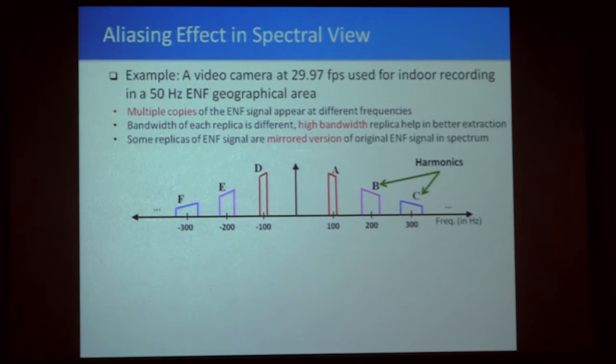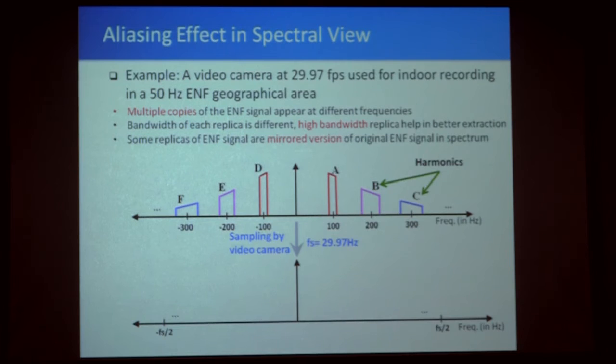So it's periodically tiling with multiples of this sampling rate. So over one period, in this sampled version, we have a periodic spectrum. We just zoom into one period, and we will find that this plus and minus 100 hertz got aliased to just above 10 hertz. So that's why we see the spectrogram before was at 10 hertz. The harmonics were getting aliased to just below 10 hertz, and then the 300 hertz harmonic got very close to